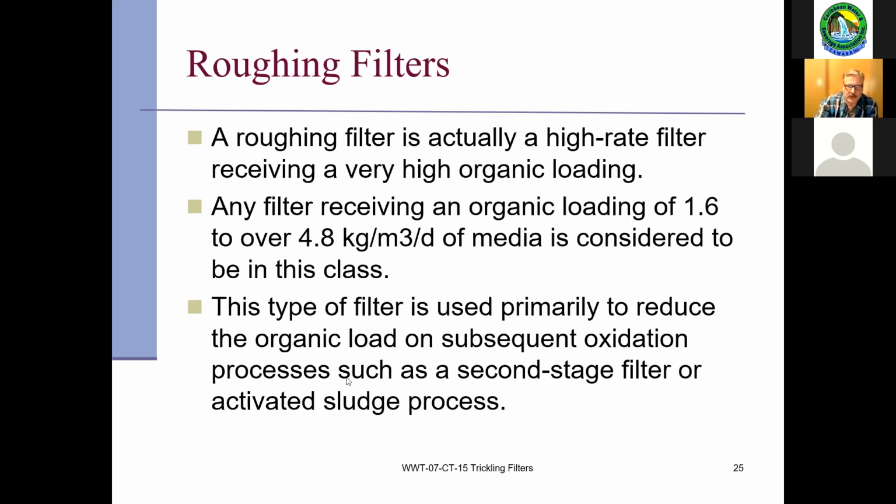Roughing filters. You're definitely going to see questions related to roughing filters as well. Basically, like we talked about, it is a high rate filter. It's receiving a very high organic loading rate. Like I mentioned, it's mainly used to reduce the primary or organic load.